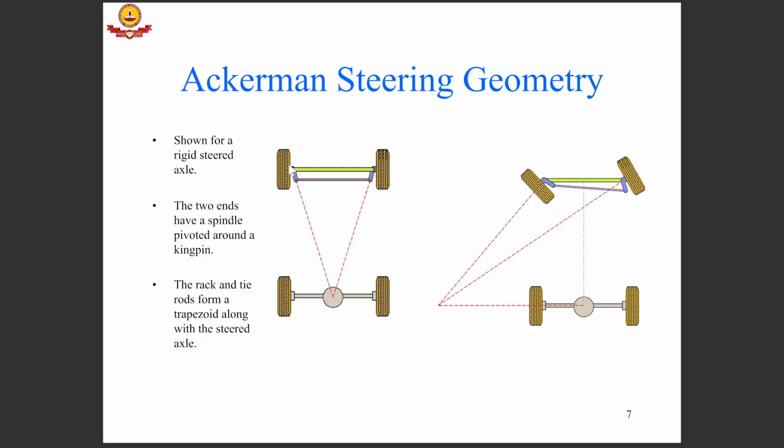Here, as you can see, a trapezoid is made and the wheelbase length forms a triangle with the front axle. Okay, if we take these two arm lengths to be equal, which they are, this becomes a trapezoid, and this trapezoidal four-bar is what becomes the Ackermann geometry.